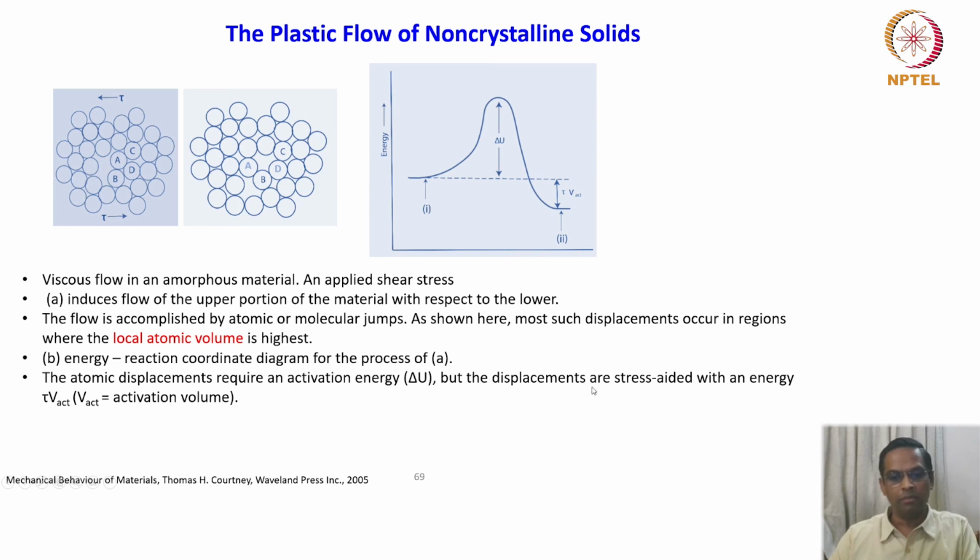But the displacements are stress aided with an energy tau V act, where V act is the activation volume. Though the atomic displacements require an activation energy delta U, the displacements are again also aided by this shear stress times the activation volume. What is activation volume? We will see this aspect in the next lecture, especially.